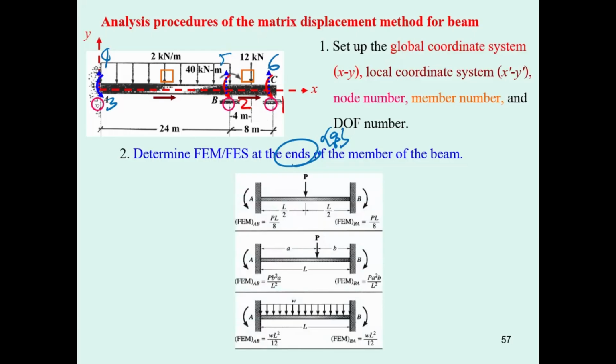However, before going to that point, again, fixed end moment didn't come with the fixed end shear. For the symmetry, the fixed end shear is going to be easy. How easy is it? Separate them into half. However, when you get this one, it also separates to half due to the symmetry. However, for this one, the fixed end shear at A won't equal the fixed end shear at B. You have to be able to determine it.